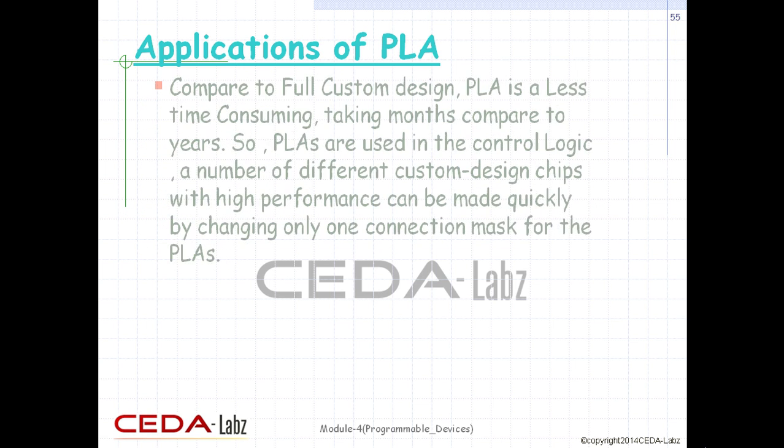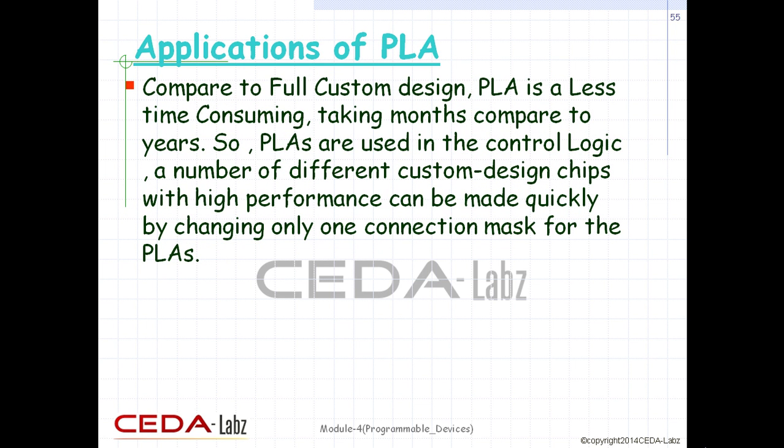If we compare PLA to full custom design, then the design time in PLA is very small compared to full custom. The design will take a few weeks in completion as compared to full custom, where it will take a year. PLAs are preferred in designing control logic as designs don't take too much time. We need to change only a few connections.